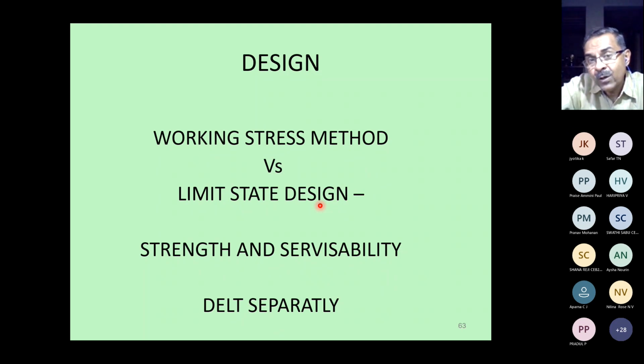Of fck equal to 30, we limit that to 6 Newton per mm square for compression, or 9 Newton per mm square for bending. Like that, an allowable stress will be allocated to that particular material. So when we check the actual stress in the beam or column, we limit it to that particular stress.